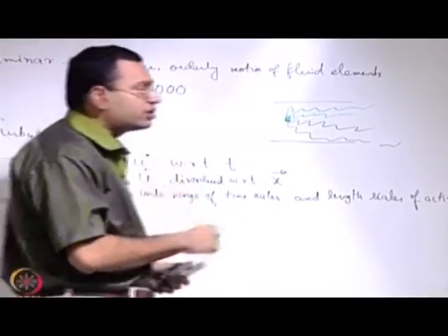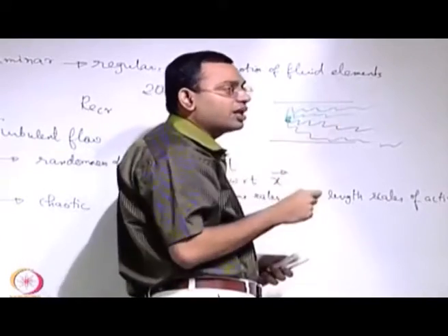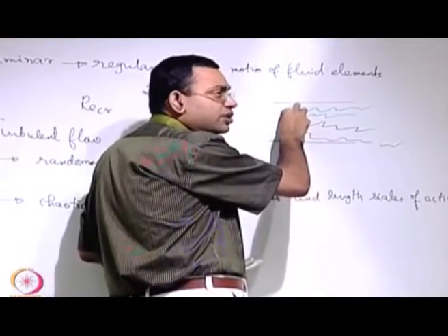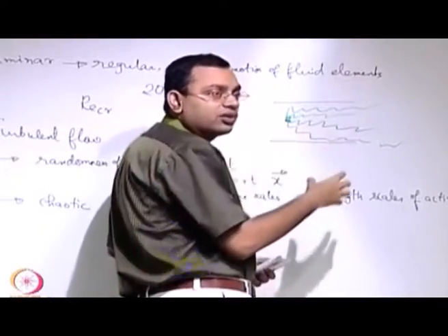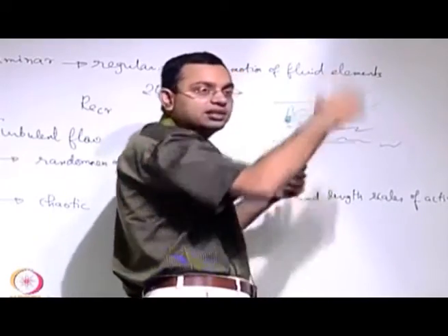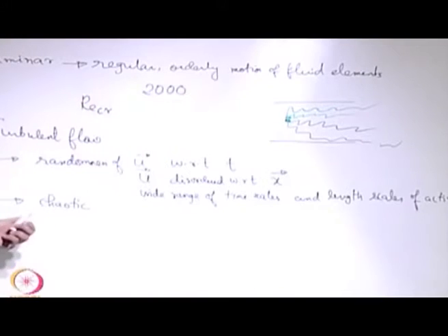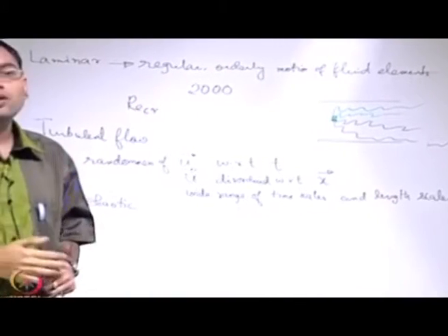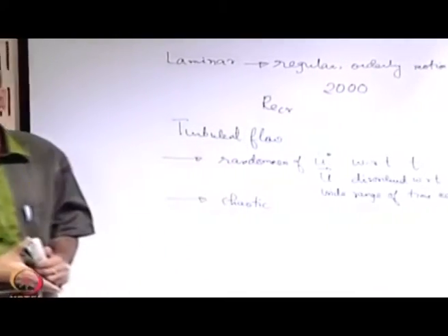So, one of the good things of this is that if you want the flow to mix well, see, two particles which were very close are now getting diffused into the flow at different locations. So the effect of whatever was there here is getting quickly mixed or transmitted to other places, and if this is the property, then we must be assured that a turbulent flow ensures very good mixing, which may be important for many engineering applications.